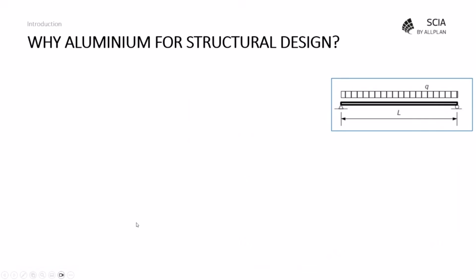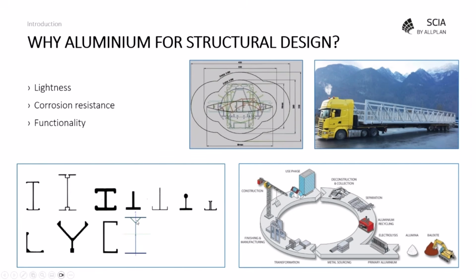Or, as you can see in the last cross-section at the bottom, you can add some triangular part to increase the torsional resistance of the section. Extruded sections can make it also possible to use easier connecting systems, for instance, by clicking instead of welding or bolting, and thus improving your joint details.